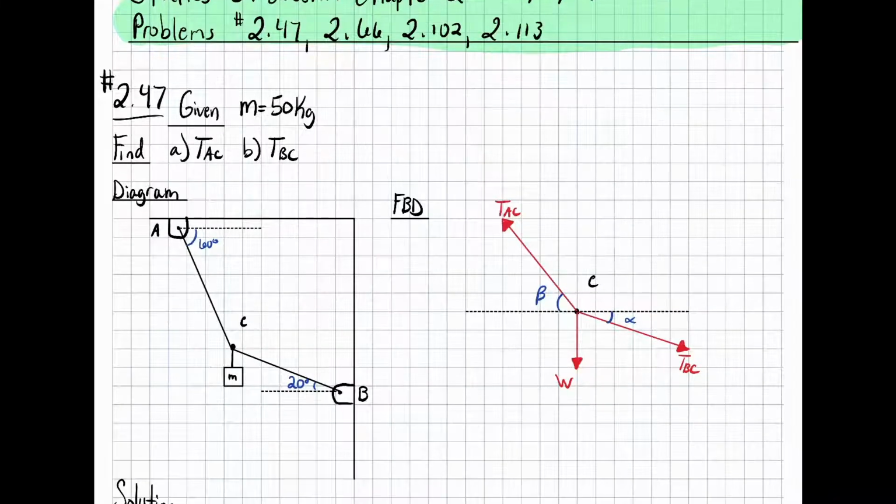Now when you draw a free body diagram, always remember to draw your coordinate plane, which you're labeling as X and Y. That's what you're going to reference as positive. And usually you need to write it with the arrows accordingly, that way whoever's looking at it knows which way you're stating positive.